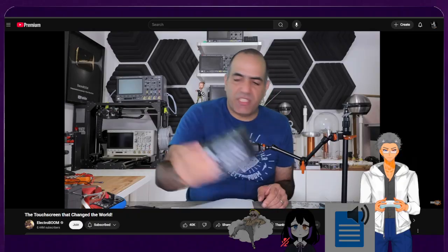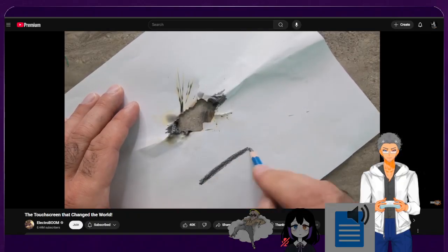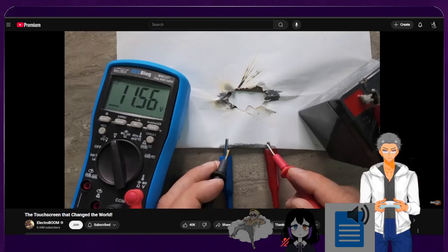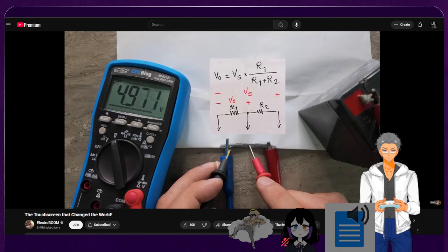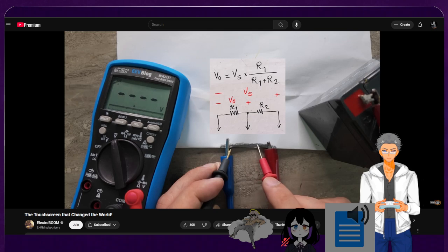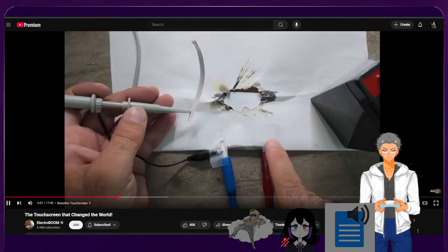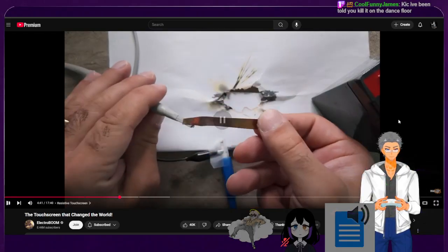Oh, I did have a battery. Trying again. So I place around 11.5 volts across it, but anywhere I connect my probe to, it is like reading between two resistors that divide the voltage down. And if I slide the probe around, I change those values and read a different voltage. This is a potentiometer. I put some tapes on these contacts to insulate them and placed a copper.